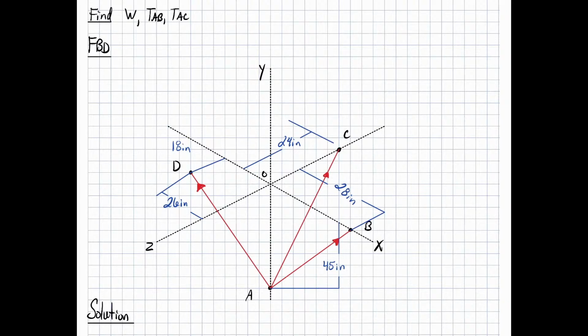That is a really good little key point to note when doing this problem, that whatever point has all three tensions or anything acting on it, whatever has the most acting on it, that is going to be your point of interest. So for this case, it's point A. If we had the hot air balloon and it was on top of the axes, so if the hot air balloon was actually up here, point A was up here, it'd be going down from A to C, or B, or D. So always keep that in mind. Whatever you write it as, so here, the question asks tension AB. A is the first letter, A is our point of interest, going up. I've seen that mistake happen a lot, so we had to clarify it. Point A is our interest.